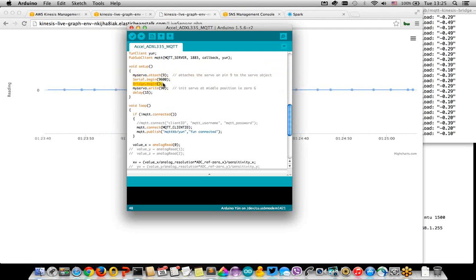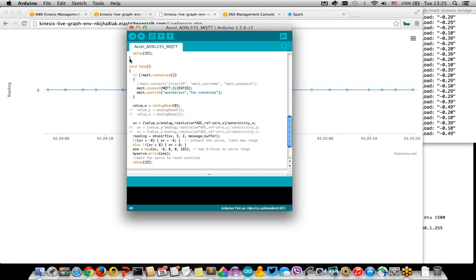We start the bridge, which gives us connectivity. And basically first I zero the servo. So I set the servo to 0, my analog display will start from 0. And then the loop function in Arduino is looping around endlessly. This is your main program.